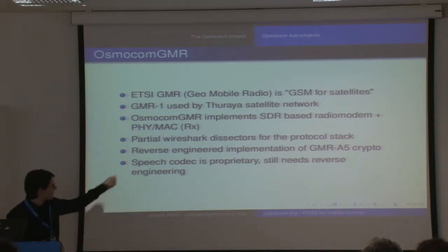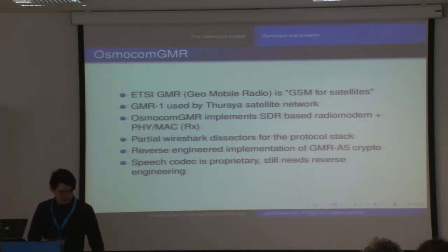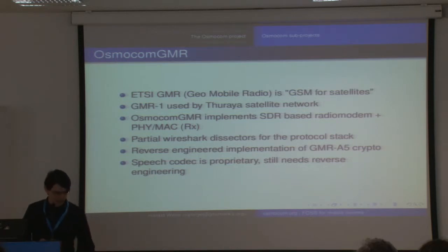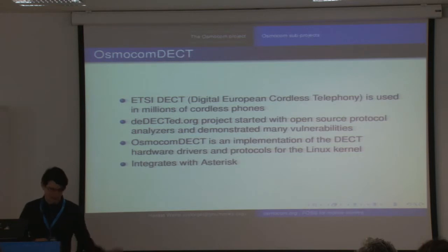But anyway, now since we started with that, people, also in the Osmocom project and associated with that, reverse engineered the crypto that is in there. There is an encryption system, but it's even weaker than the one that we have in GSM, so you can break it in near real time. The only thing that was slightly harder, the slide is actually outdated, is the speech codec, because the speech codec by which the speech is compressed is completely proprietary and not documented anywhere. And one of our core project members in Belgium has actually managed to reverse engineer the speech codec, and now we can also decode the speech used on the satellite system. So yeah, that is already, as the slide says, slightly outdated.